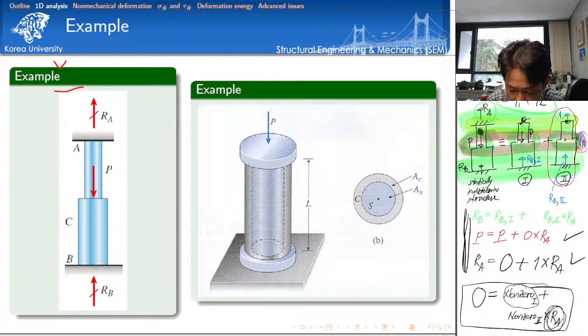My structure system is here, okay? This is my structure system. I didn't shade the support intentionally. It doesn't include it. So make sure that the reactions are treated as external forces, okay? If you treat it in that way, you can solve this problem. For the detailed calculation procedure, please talk with my TA, and he will cover the solution procedure for the compliance method. So now let's talk about the second example here.